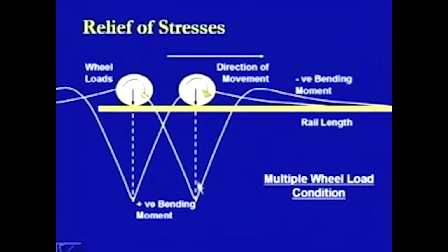Similarly, there is a positive bending moment at this location like this. Now, if we take the diagram of this bending moment with respect to the point of contraflexure and further the negative bending moments which are being induced, what we found is that for this one, if this is the max positive bending moment and this is the positive bending moment for wheel 2, and if we go backward, then at this location we are getting the maximum negative bending moment because of this wheel load.